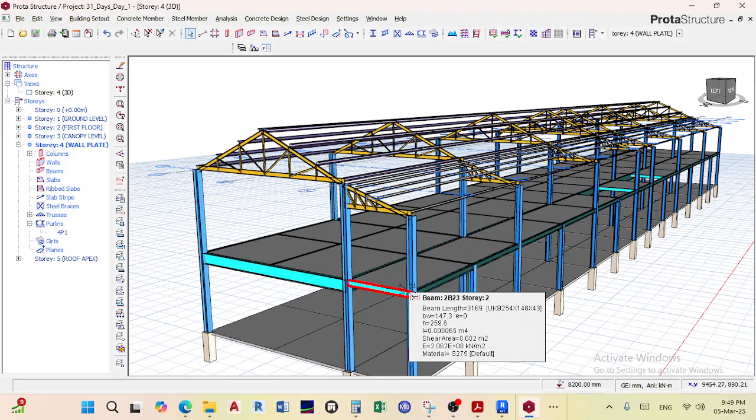But then this is for a 200 by 400 column and a 200 by 400 beam. If I can increase my column to be like a 400 by 400 column, it can hold something like a 400 by 600 or 400 by 800 deep beam. And then I could even span it for like 6 or 7 meters. Why? Because it's deep. It's the 800 depth and the 400 width.